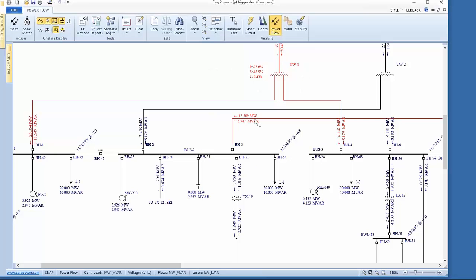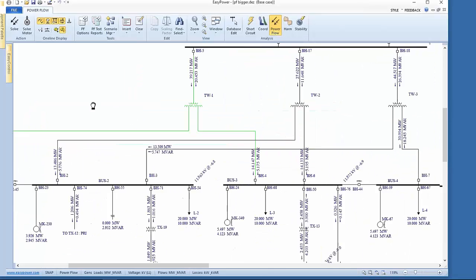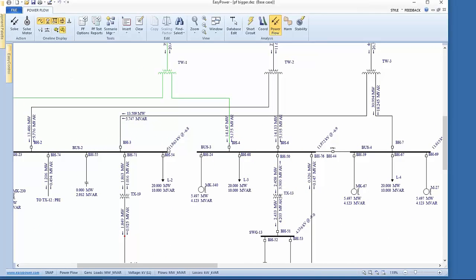And so that's what's generating these indications in red. And then finally, the voltage violations, we're not seeing anything that's giving us a voltage violation just of itself, which is a 10% overload.